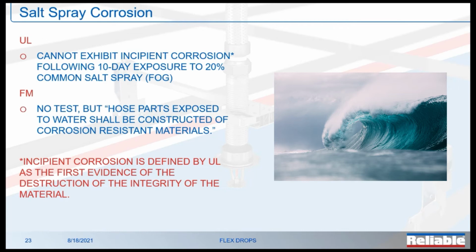We make the point when we talk about this that the pass-fail of the sprinkler test is not how it looks. It's how it functions compared to its out-of-the-box state after it's been exposed to these tests. So what we're looking for with regard to sprinklers is incipient corrosion as well. We're not talking about the aesthetics. So kind of keep that in mind. There's a little bit of a correlation between that salt spray test here and the salt spray test and other tests of the fire sprinklers themselves.